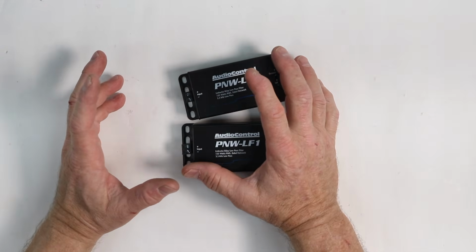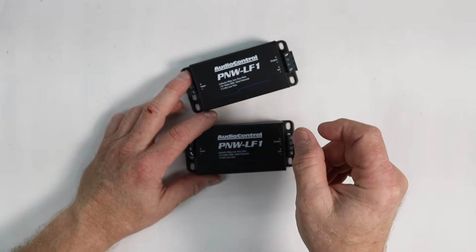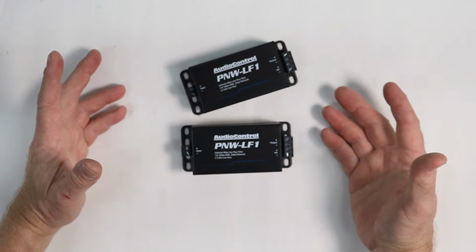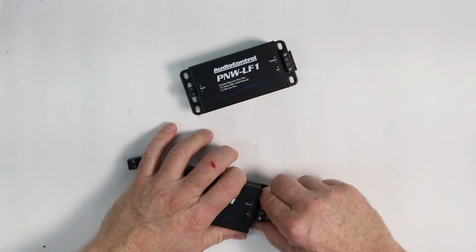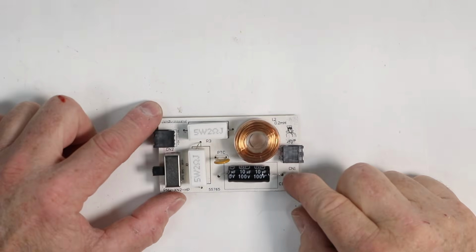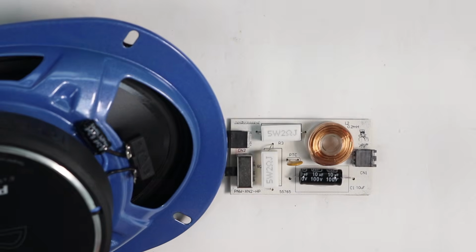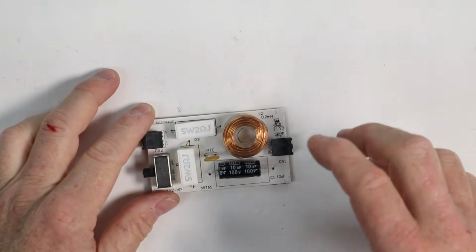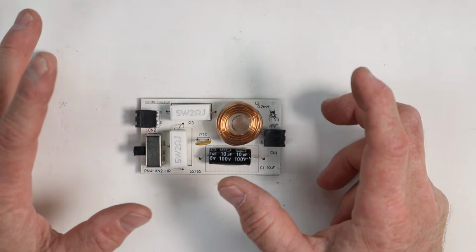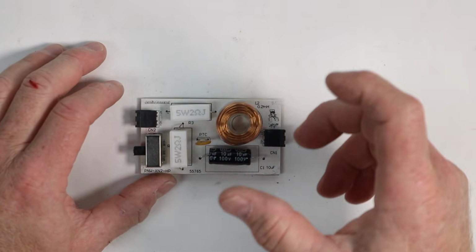A capacitor is a 6 dB crossover. A cap and a coil is a 12 dB crossover. Two caps and a coil, or two coils and a cap, would be 18, and then two caps, two coils would be 24. It could get really complicated. Let's take apart this passive crossover and see what's inside of it. Find out if it's a 6 or 12. And this, in fact, is a 12. Here's the cap, here's the coil. Unlike this guy, which is just a cap, 6 dB, 12 dB. That means that this can do a little bit better job blocking the lower frequencies from getting to that tweeter. And it gives you a little bit more control over how you can play it, as well as increased power handling.